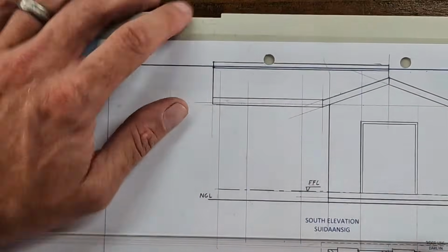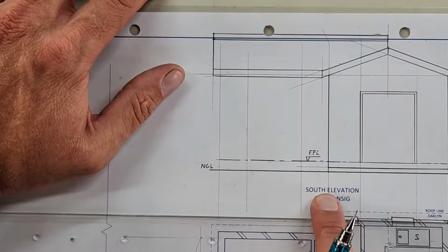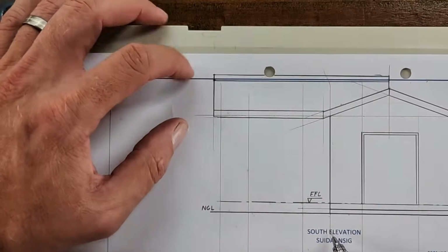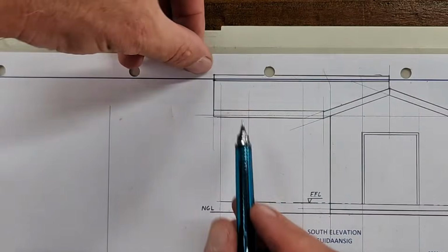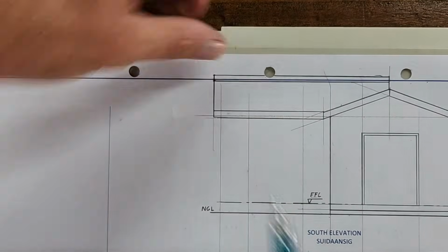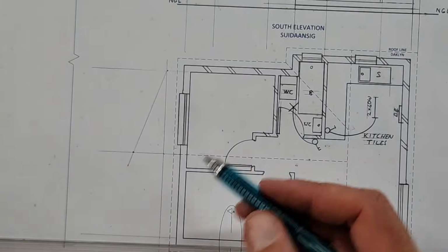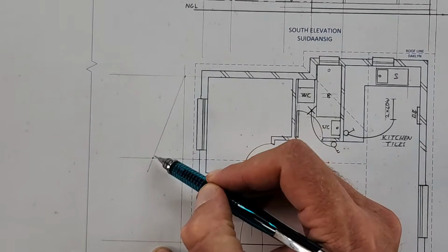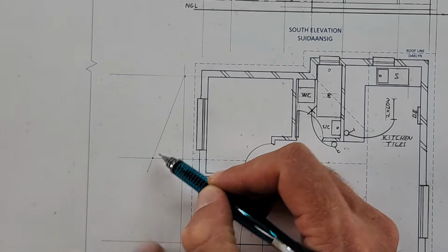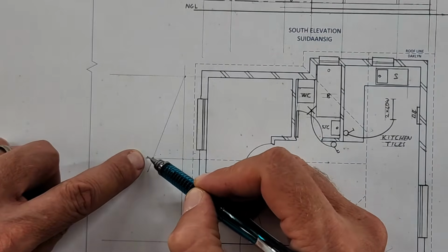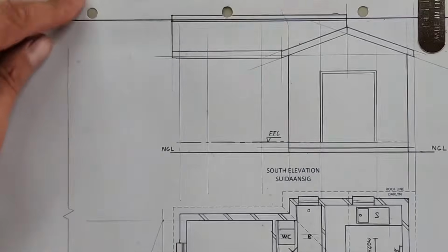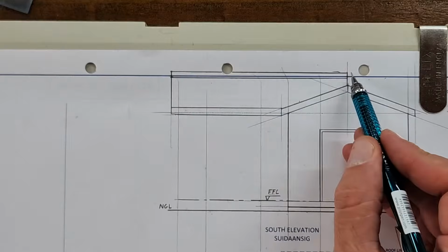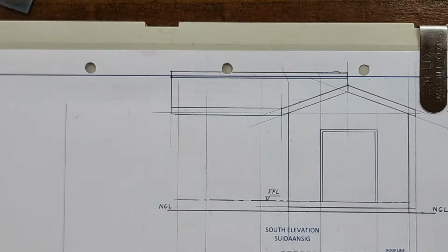Sorry, my spacing here between the south and that should have been closer. This should fit just underneath that line if my spacing was correct. But that height there was determined by an auxiliary view that I just did here, on the inside of the walls, 20 degrees. That gives me the height of that roof truss, but I still have to add the purlins plus the roof sheeting. And that's that little bit. It's actually your wall plate that runs on top of that. But that height I had to add.